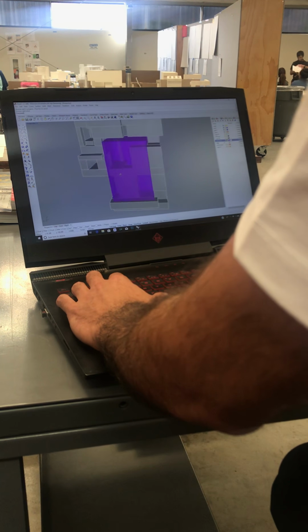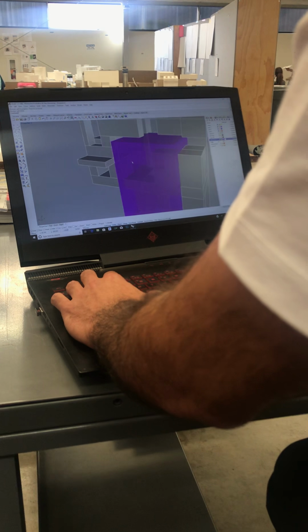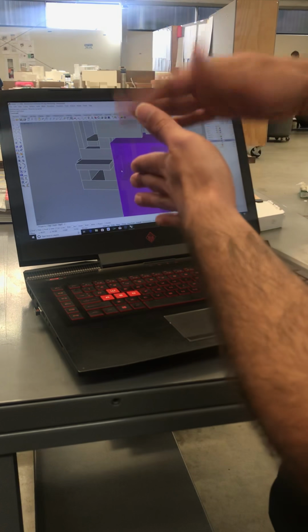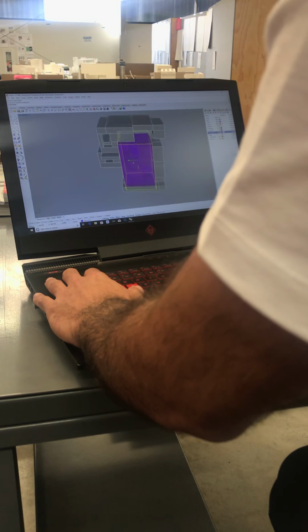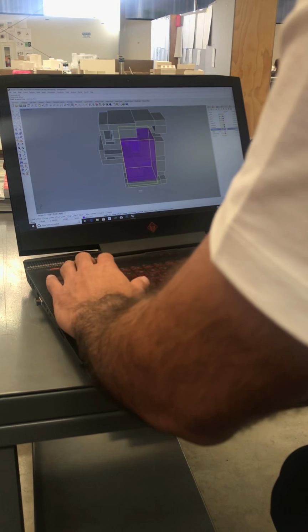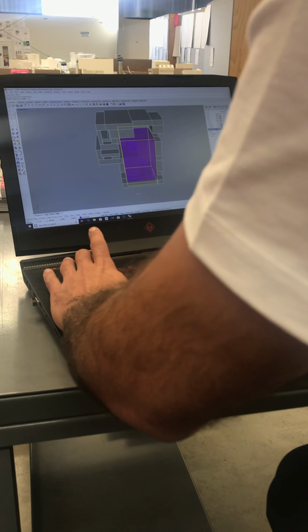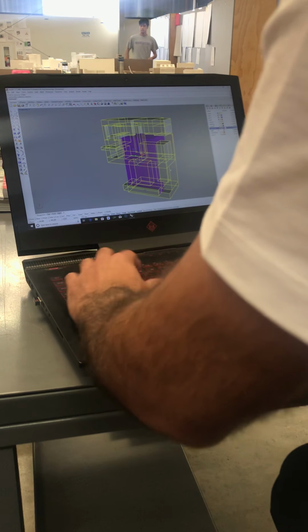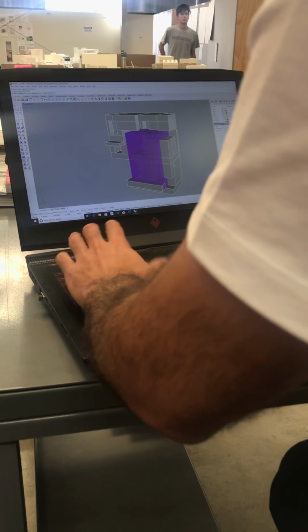and it failed again. So it's probably because it's lining up with this face here, because it doesn't know whether to keep that face or not. So I'm going to move it one module in this direction. It's 1/2 inch. This direction. Let's give that another shot. Boolean split.